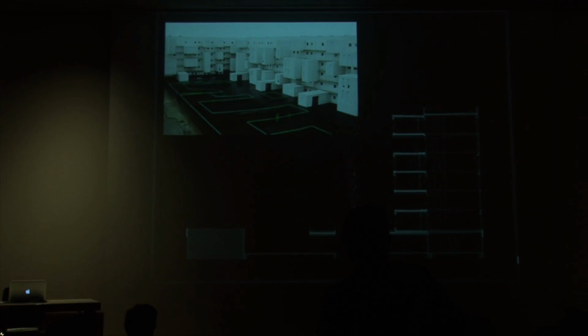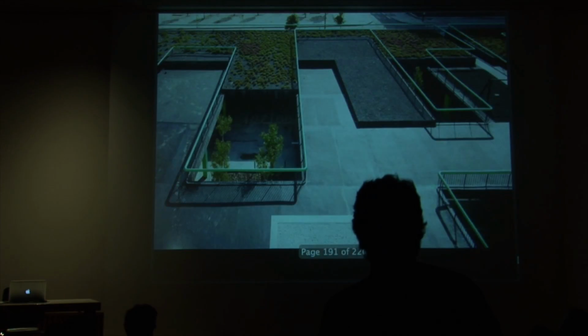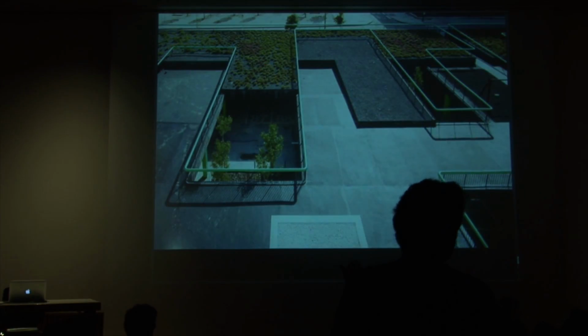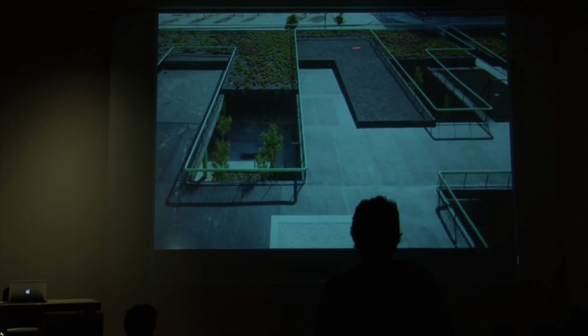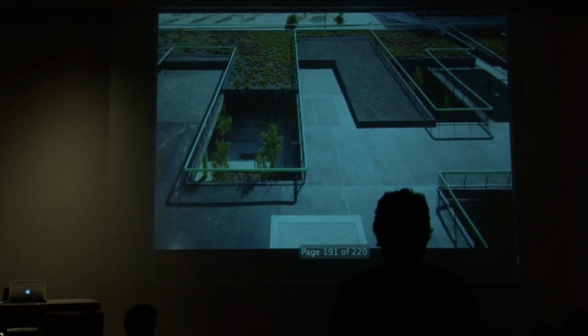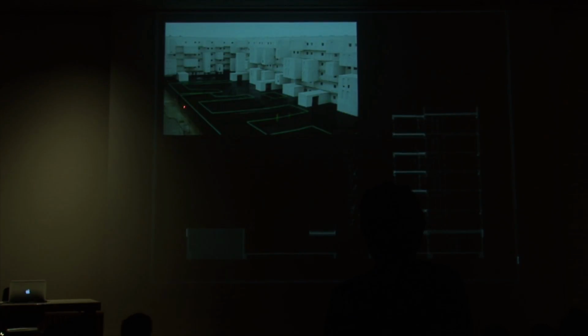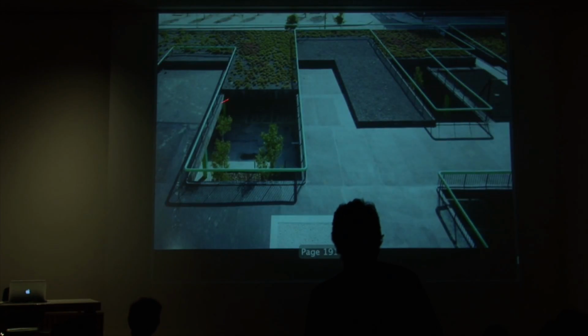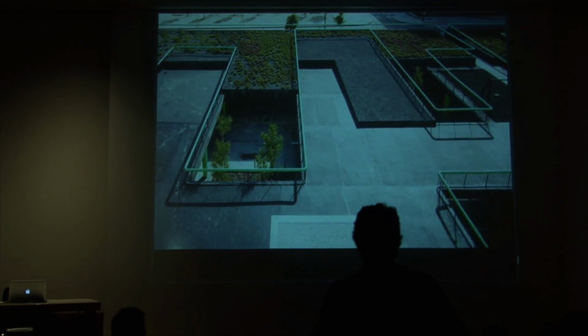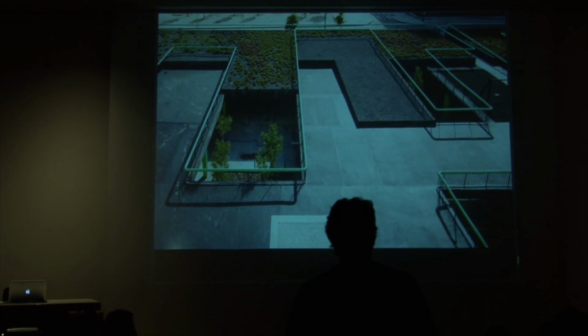So the parking is only half floor underground, and that allows us to block the access to the site just with a normal railing, because that railing, if you combine it with the 1.5 meters that we have lifted the underground, let us have this space completely open to the outside.